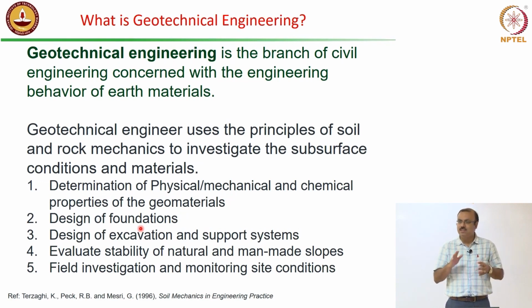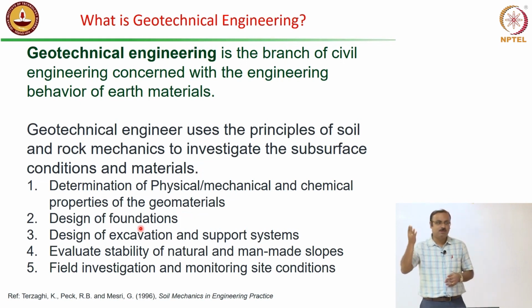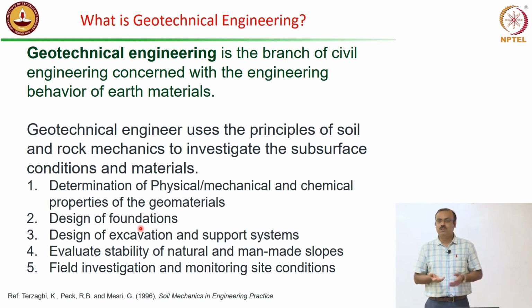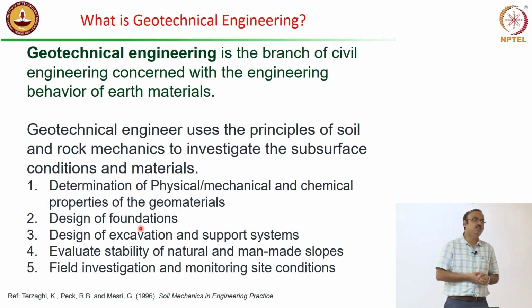and it's very challenging, because there is a gentle slope, and at the same time it's like a helical type of network. Now, unless the surface of the hill is stable, how are you going to construct this road? If there is a continuous fall of rocks, nobody will be able to drive on that road, right? So the geotechnical engineer's responsibility is to ensure that the slope of the hill is stable. If it is naturally not safe, then you have to cut the slope, do some engineering, so that the slopes are stable and not falling onto the road.